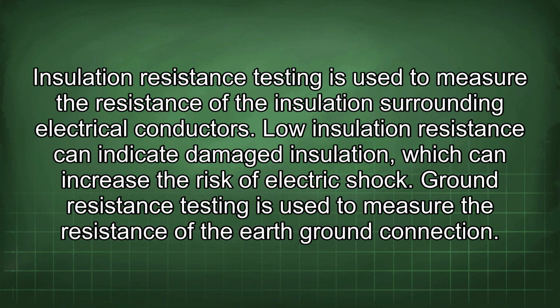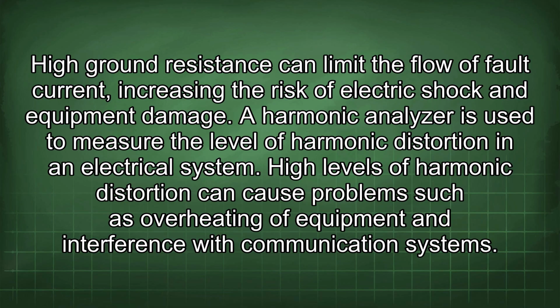Insulation resistance testing is used to measure the resistance of the insulation surrounding electrical conductors. Low insulation resistance can indicate damaged insulation, which can increase the risk of electric shock. Ground resistance testing is used to measure the resistance of the earth-ground connection. High ground resistance can limit the flow of fault current, increasing the risk of electric shock and equipment damage.